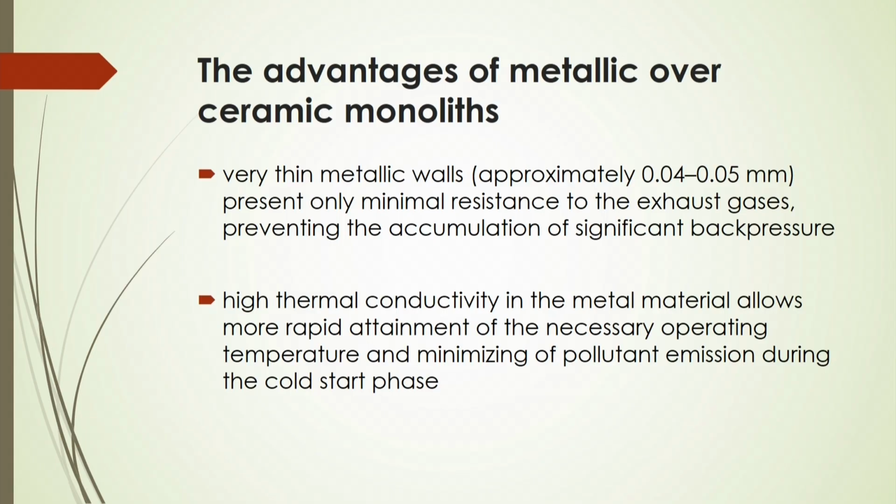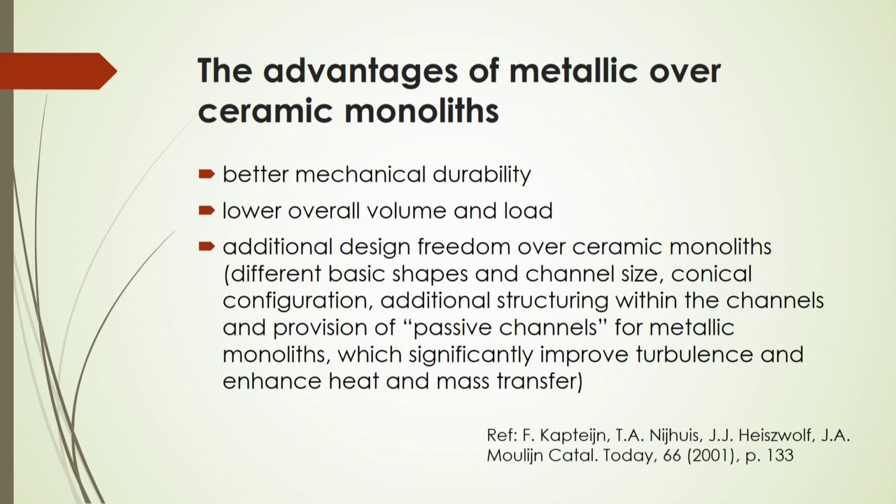The high thermal conductivity of the metal material may allow more rapid attainment of the necessary operating temperature and minimize the pollutants emitted during cold start phases. So, you can have this type of advantages of metallic over ceramic monoliths.